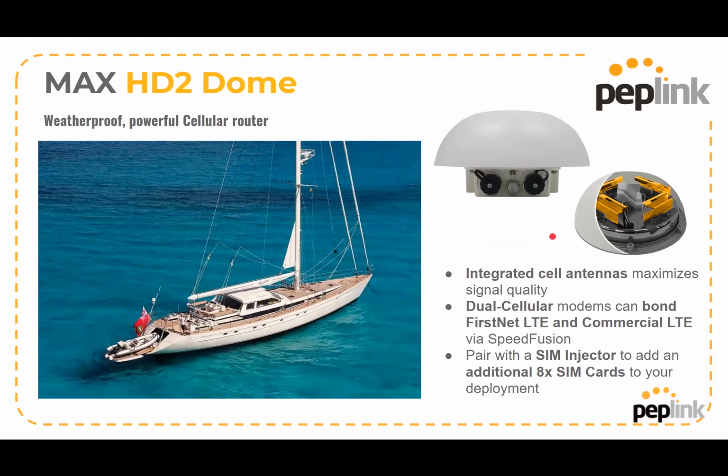Now, the reason we did that was, as people know, especially in transportation and outdoors, to gain the maximum signal strength, A, you need to point the antenna towards the source. B, you want to get as high as possible to get away from lower level obstacles such as buildings, metal bars, trees, not trees, but metal bars and other construction that may interfere with radio signal.